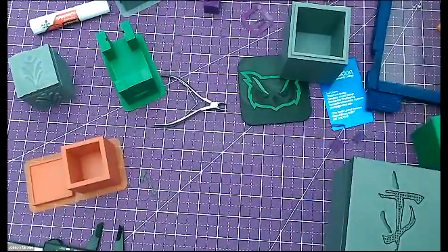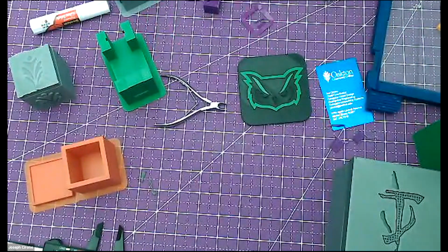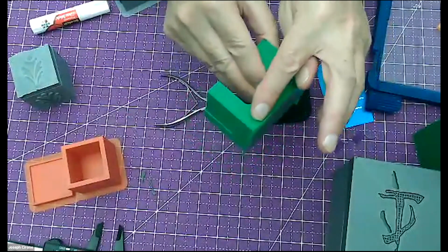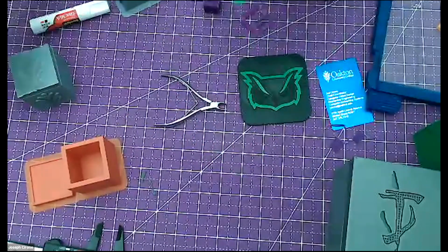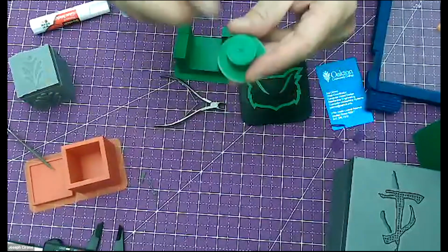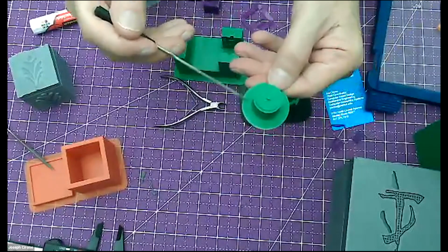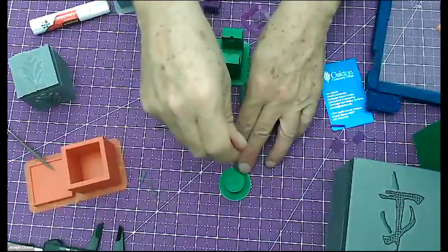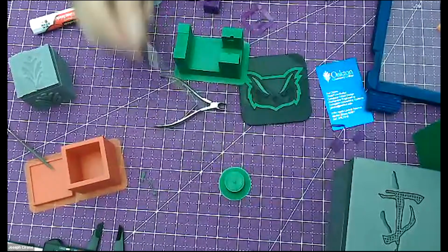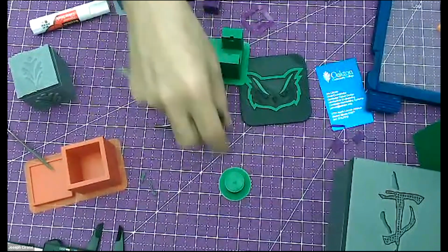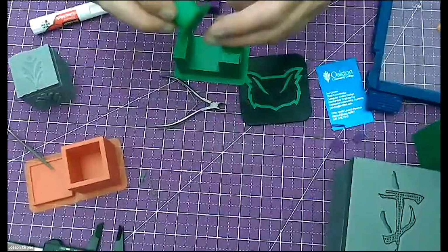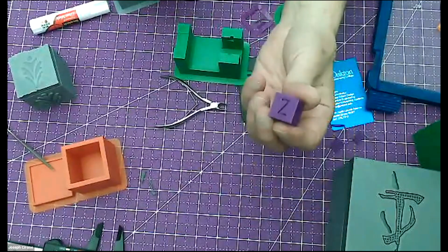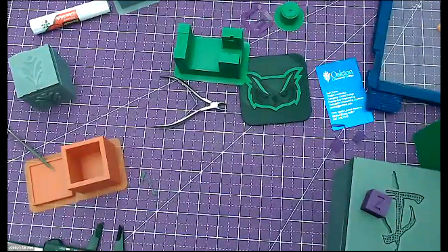And then as we go into our next project, here's one of our tape dispensers. Make sure that you brand it. This was done with AutoCAD. I can tell because they use the bonus tools to subtract the text out. And here's the wheels. I find that when we print the wheels, what works best is to print them in this orientation. And you can see that I'm using build plate adhesion here. The build plate adhesion will allow us to print this. And what we find is that if we print them in this orientation, the round shapes are more round. When we print them in this orientation, they tend to be a little bit elliptical. As you can see, when I calibrated and measured my view cube, we don't necessarily get perfect dimensions on that. And so that's some of our projects.